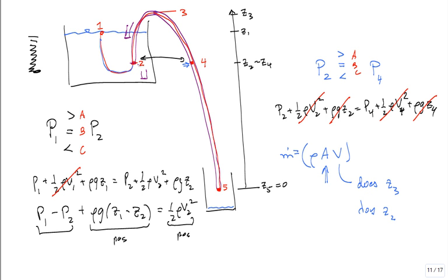As long as you don't get it where it comes out. If you get it out, it breaks the siphon, it won't work. Or if you get it too close to the bottom, it could be blocking the flow into it because it sits on the bottom and sucks on the bottom. It'll actually pull itself down and stop the siphon. But no, the elevation doesn't matter. You can change the elevation in the tube a little bit. It won't change the flow.